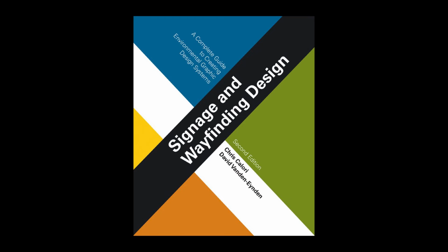Glass sign panels typically need a support structure, which is usually visible due to the transparency of glass. Supports can include a continuous frame that surrounds the sign perimeter or individual supports at strategic points. Although opaque glass panels can be supported by hidden structures, frameless glass signs should always have eased edges, which are very slightly beveled at a 45-degree angle to prevent chipping and ease the sharpness of 90-degree cuts.